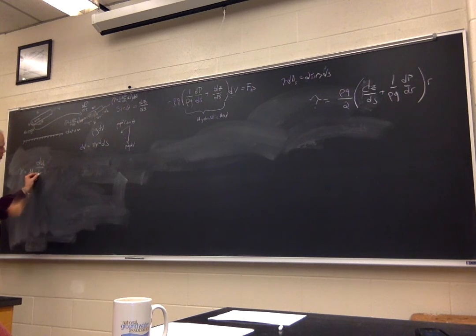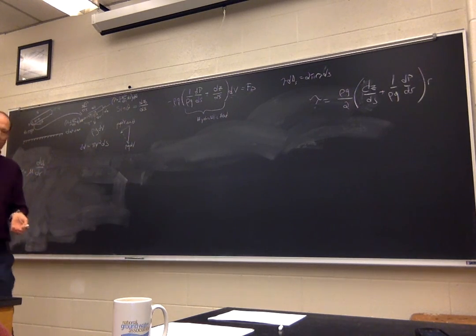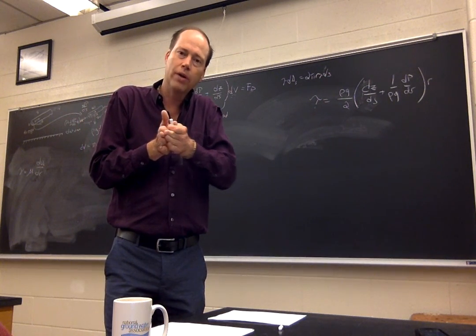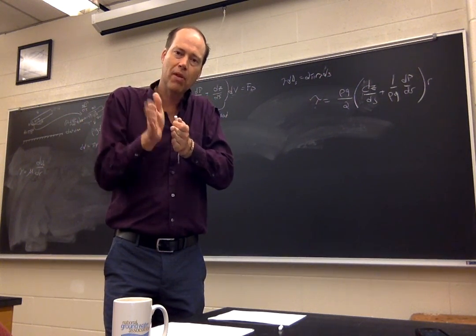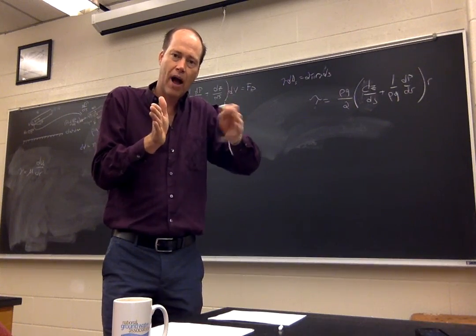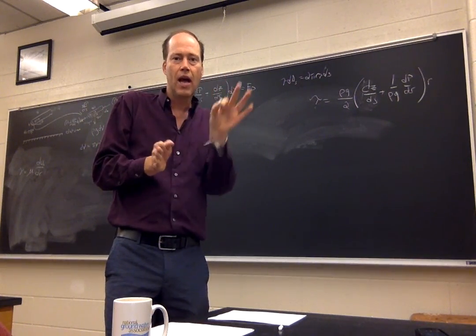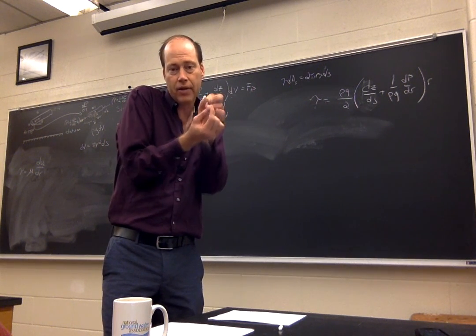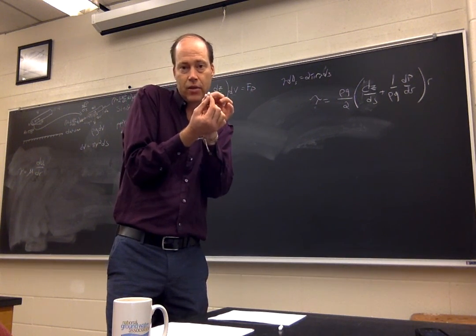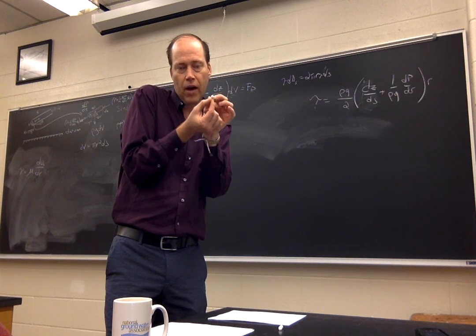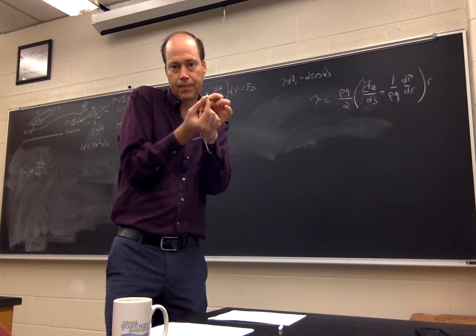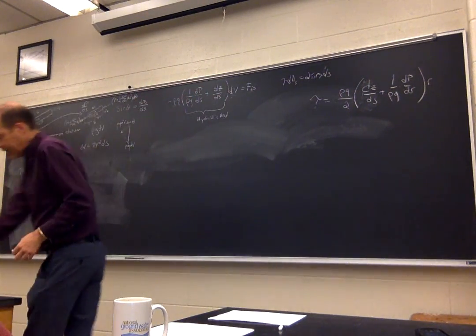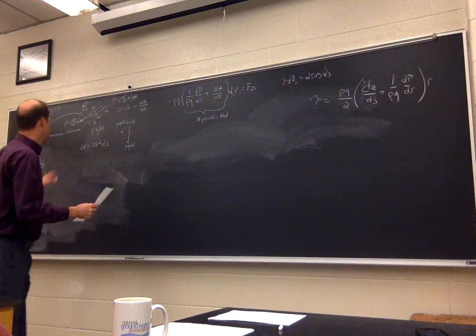That's why it is in terms of r, not x, because last time x was just a coordinate, the distance from one plane to the other plane in the crack. Now we have a cylinder, and the only direction that matters is with respect to the center, r being the radius of the pipe. So that is our construct of Newton's law of fluids.